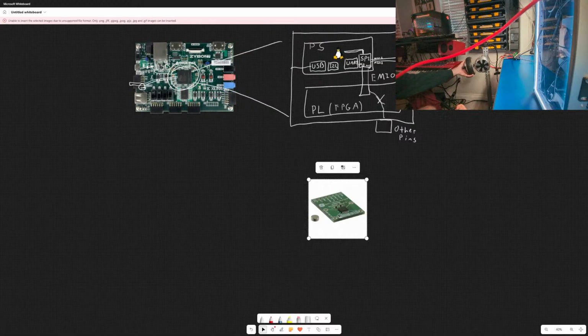I'd rather have an absolute encoder, because if you're working with a robotic quadruped, you can home the joints. It's just you're going to have an initialization sequence at the beginning of the robot moving every single time. The robot will have to move to a certain point, hit its limit switches, understand, oh, that's the limit, and then start incrementing from there. If you have an absolute encoder, you don't need to do that. You just turn it on and it knows exactly where its limbs are at any point in time. So that's another benefit of having an absolute encoder.